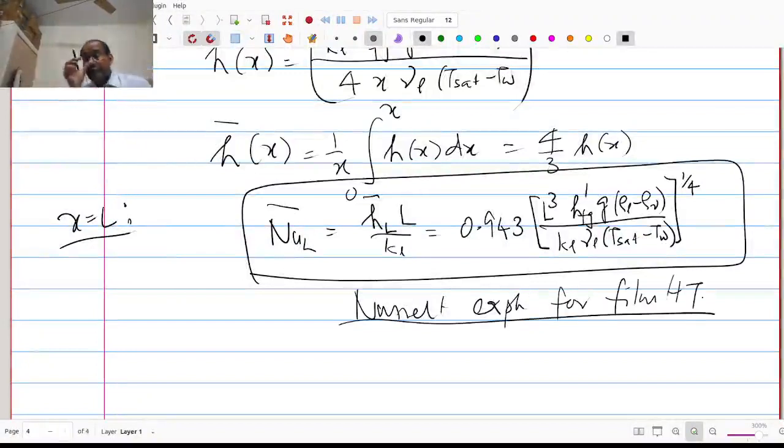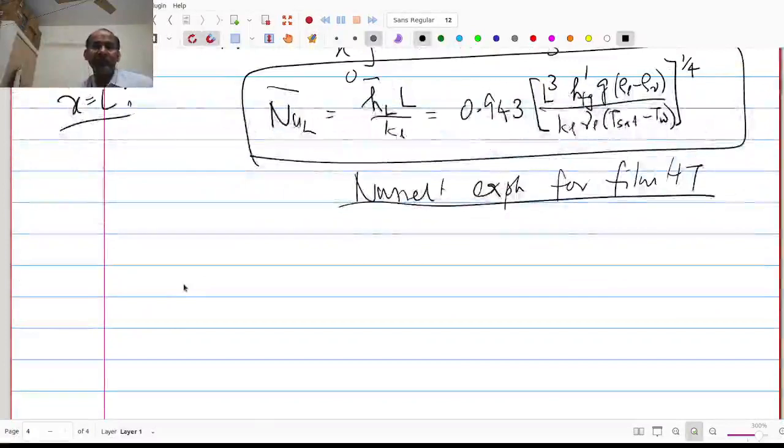So basically, if I have falling film condensation, then in falling film condensation you get the Nusselt number given as this expression. Now this expression basically assumed that the temperature profile is a straight line, but if I could do the integration using the proper integral method without assuming that straight line, you assume a temperature profile, substitute the boundary conditions and get the temperature profile, and do with that, then you get a better expression.